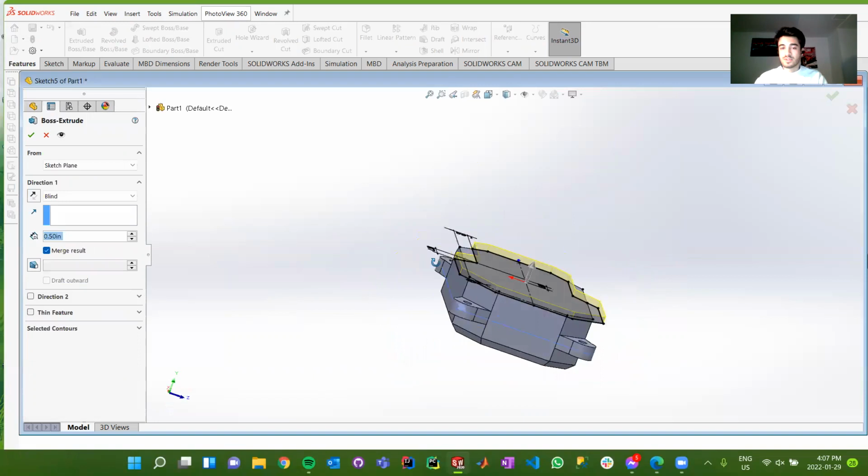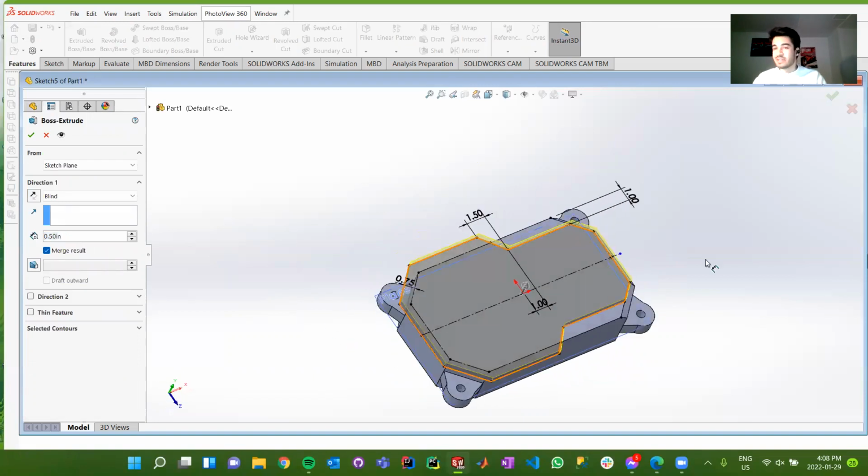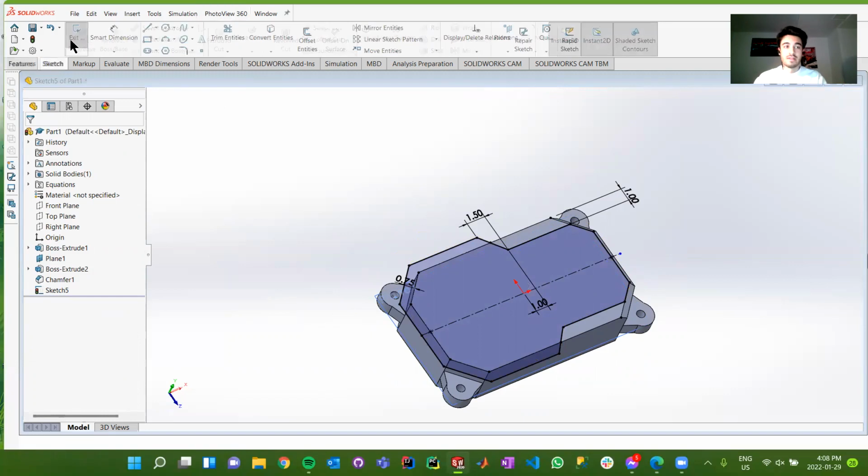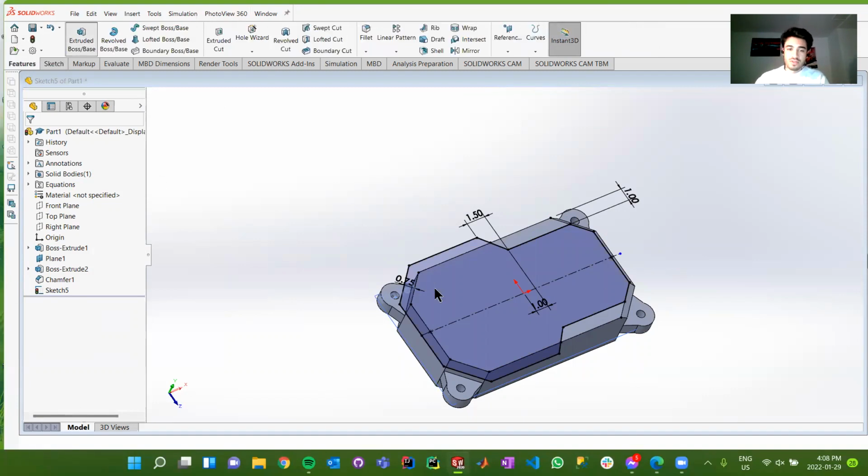And now we have the option to extrude essentially this paddle looking thing right here. It's a little peculiar at first, but you'll see where it comes in once we actually get going with the other components of the drone itself. So what I'm going to do is I'm just going to check how much we extruded by, again, just to keep it consistent. So we went up by 1 inch. We'll do the same. So I'm going to press extrude.